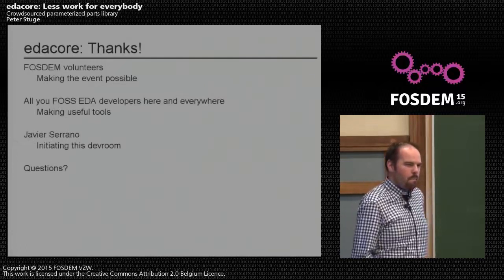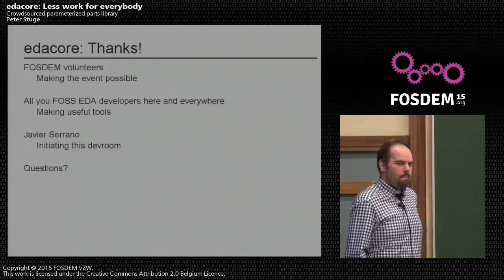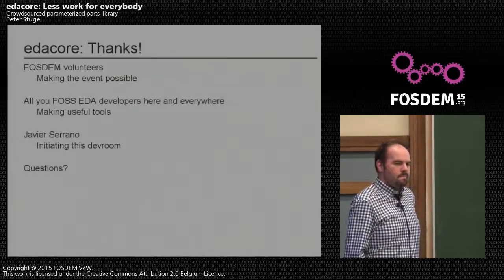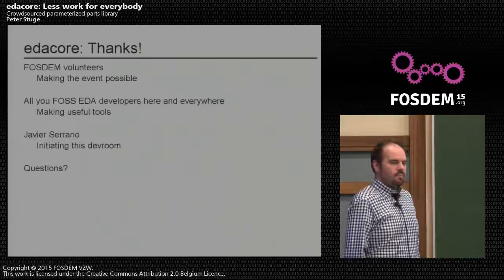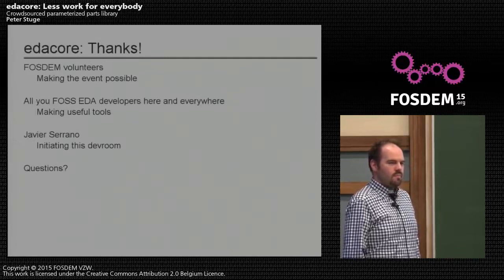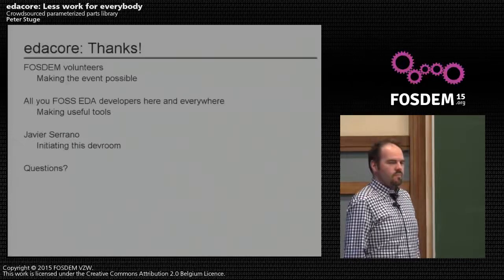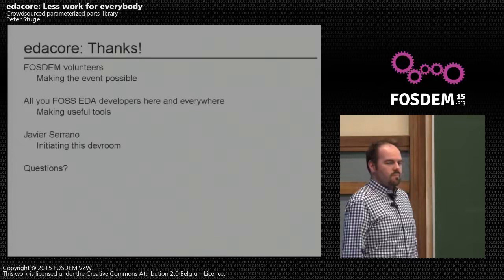I came across a similar idea just from another direction. I want to take a schematic from everywhere and repair this board. So I need something like an instruction: how to start, which point to measure, and so on. My suggestion is to simulate different errors, stuck-ats, bridges, shorts, and so on, on the board, get out the data, compare the data, and just build an instruction.